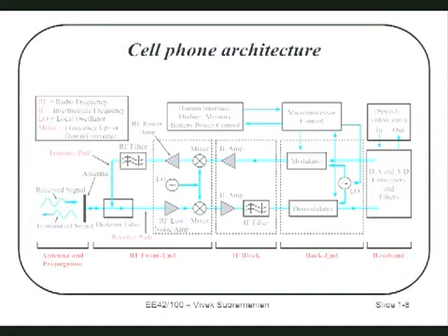A digital system, at least digital as we use it for most applications that we're going to talk about, is a system with discrete levels. For example, if I have a 5-volt power supply, a digital system might represent 2 levels, one level at 0 volts and another level at 5 volts. An analog system will be continuously variable. For example, a sine wave would be an analog representation.